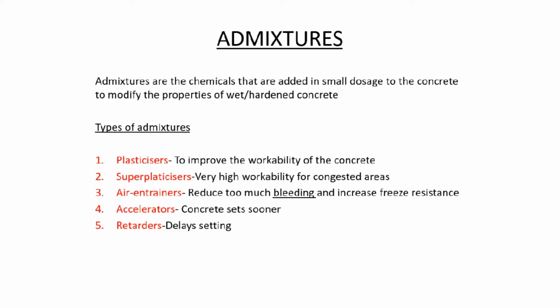Accelerator. An accelerator speeds up the setting of concrete, which means the concrete sets sooner. Retarder delays the setting of the concrete, which means once the concrete is poured or cast, it will take time to set.